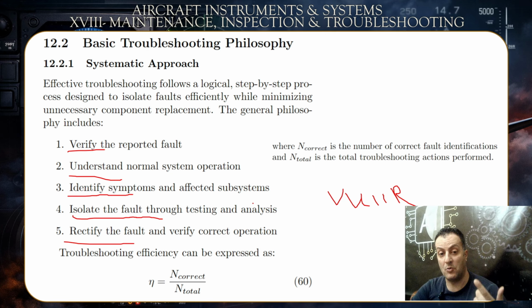So VUIIR: verify, understand the normal system operation, then identify the symptoms, what is going on, then isolate the fault to check what systems have been affected through testing and analysis, and finally rectify the fault or the problem.